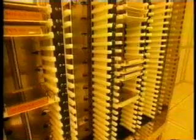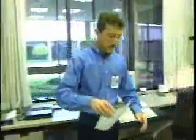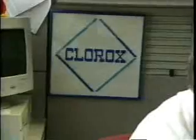So we may pick what we would look at as an average complexity wafer and then translate the least complexity wafers and the most complex wafers by some ratio into those equivalent units of average complexity wafers in order to understand both the capacity of our factories, in order to manage the cost of the factories, and look at profit margins across a particular product line. And that gives us just one more means of being able to manage cost, be able to understand cost, and manage the diversity of products and processes.